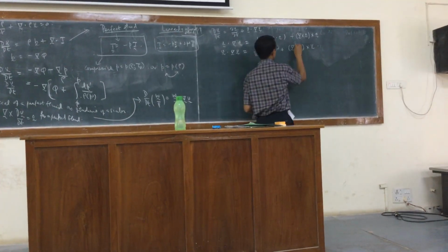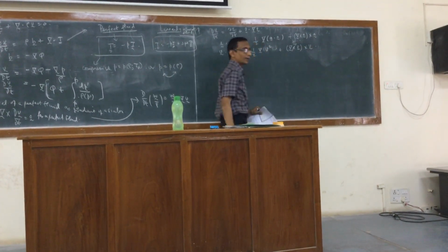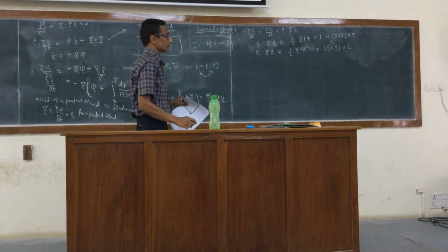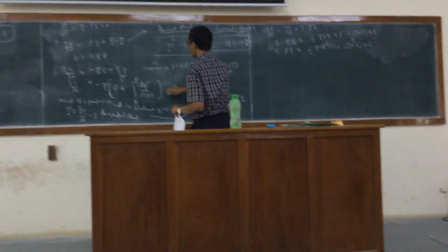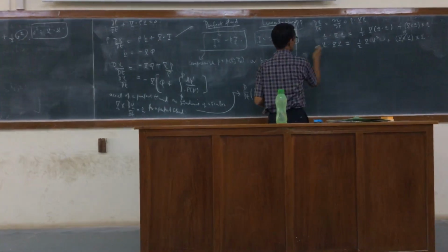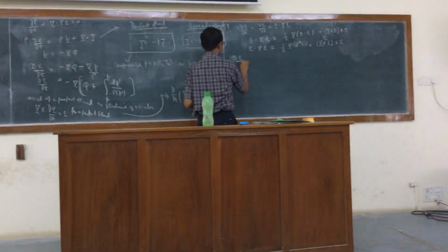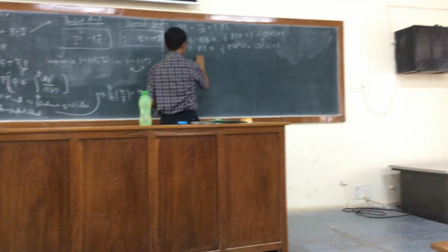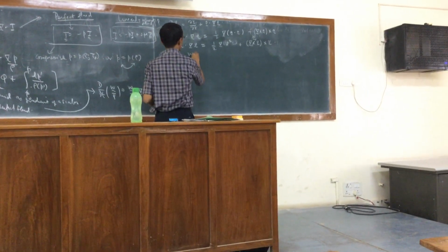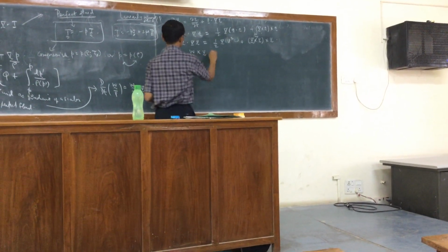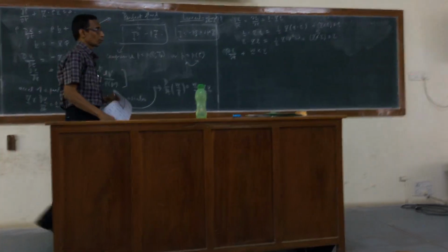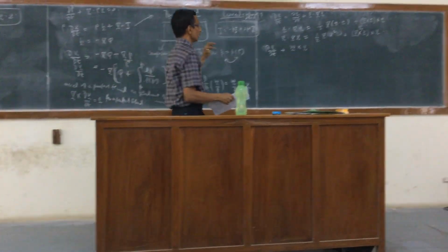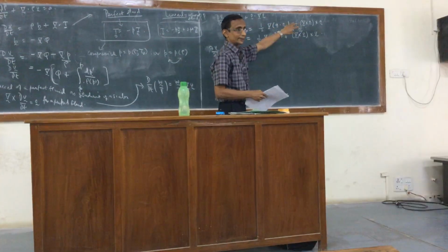Curl of the velocity is nothing but the vorticity vector, and so this is what I get from E dot the gradient of V. So when I substitute it here, I will get dV by dt, which is this. So this will be dV by dt, right? Plus the cross product of the vorticity vector with the velocity vector. Now I am going to bring this to the right hand side.